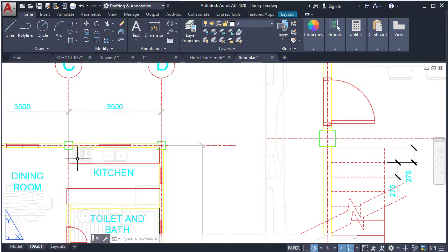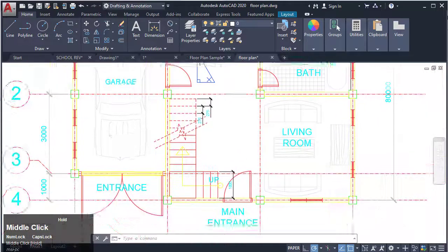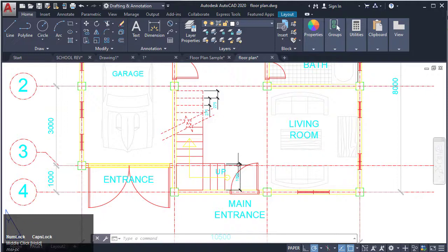The viewport scale on my left shows a dimension style that is set to 1:100. The viewport scale on my right has a dimension style set to 1:50 and a corresponding viewport scale also of 1:50. By using this setup, the appearance of my dimensions is identical in size. However, a problem is generated if we take a look at the setup of the staircase in my 1:100 drawing.